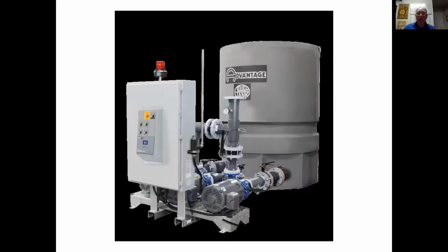And then a control cabinet or control console with switches to turn the pumps on or off, and a controller that will control the thermostat to turn the tower pump on and the tower fan on to maintain your set point temperature. And keep in mind, with the tower system, 85 degrees is the typical set point temperature, but you can set it at any temperature that you want. You can set it at 70, 60 degrees if you want.